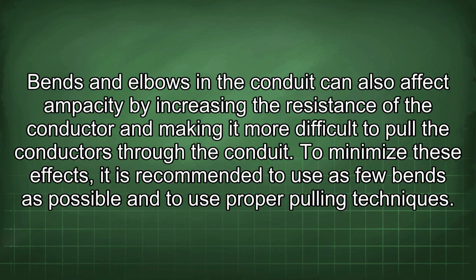Bends and elbows in the conduit can also affect ampacity by increasing the resistance of the conductor and making it more difficult to pull the conductors through the conduit. To minimize these effects, it is recommended to use as few bends as possible and to use proper pulling techniques.